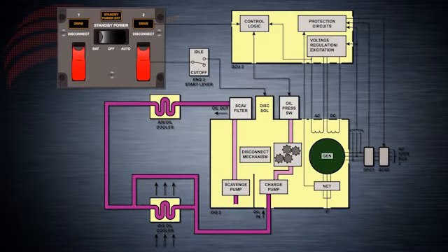Let's talk a bit more about the primary source of electrical power on the 737NG, the engine-driven generators. There are 2 generator drives, one for each engine. The generator drives are the normal source of AC power. If they were to fail, the APU and ground power may be used. Each generator drive has the following relevant components: an integrated drive generator, or IDG, and an IDG air-oil cooler.